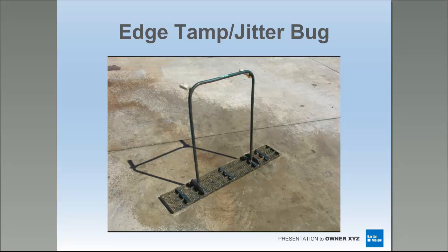Now that's great if you're going for that sand polish, because right on the edge is where I find this tool most beneficial, because your curl is going to happen right on the edge. If I'm trying to avoid any aggregate exposure, the more cream I have on that edge, the better. If that slab curls an eighth of an inch and I don't have that cream layer or coverage, I could get to that aggregate pretty fast. So this tool helps me avoid that, keeping a little extra cream on my edge.